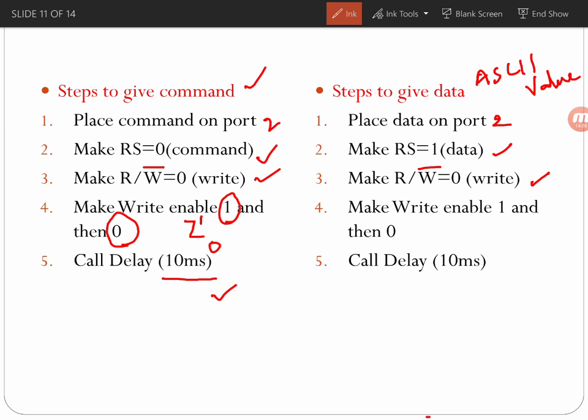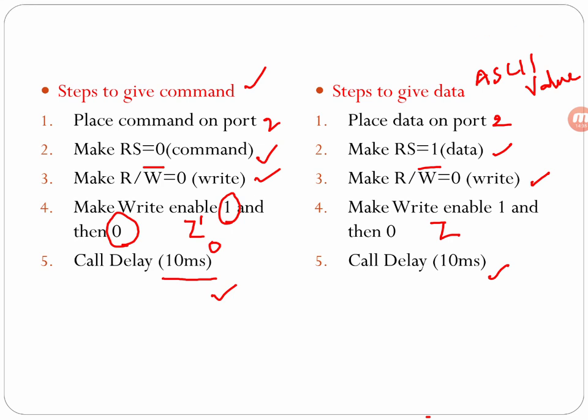Then make the enable pin high to low, it is a latch, and then call for the delay, which may be approximately 10 milliseconds.